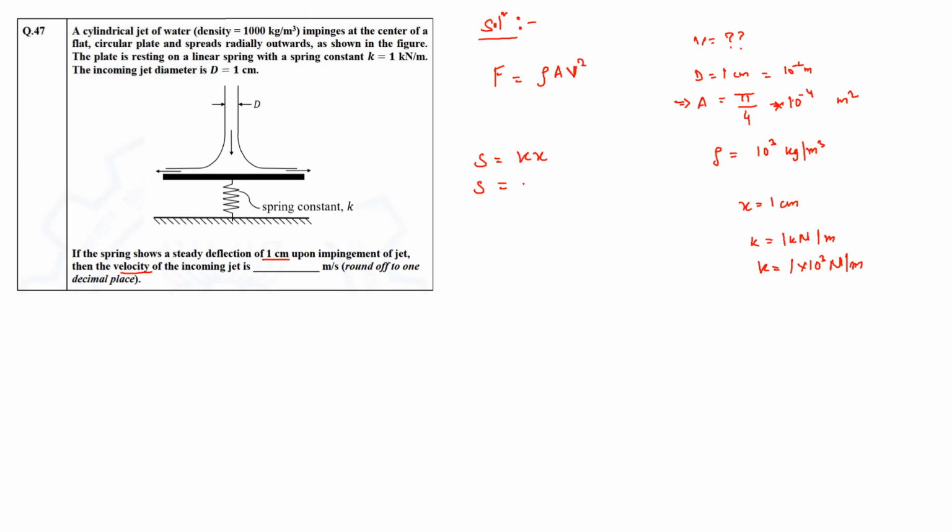So S for us is 10 raised to the power 3 into 1 centimeter, which is 10 raised to the power minus 2 meters. Now you just do this force balance, where the force applied by the jet onto the plate is equal to the restoring force of the spring, and then this just gives you the answer.